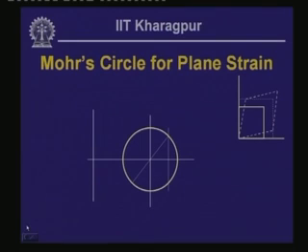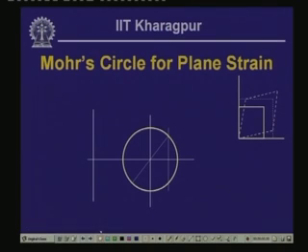and we will be following this convention while plotting the Mohr circle for the strain. Now, exactly along similar lines as we did in case of stress evaluation, we will be computing the strain identically using the Mohr circle of strain. Now, let us look into how we do that particular job. Here, let us say we have strain at a point, or this is a small element where the lengths are dx and dy, and it has undergone strain epsilon x, epsilon y and gamma xy, and from this configuration you can make out that all quantities are positive,